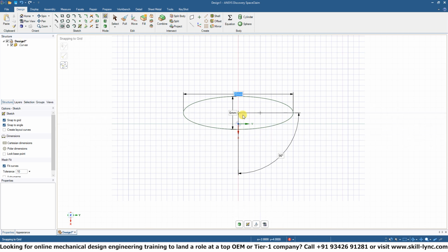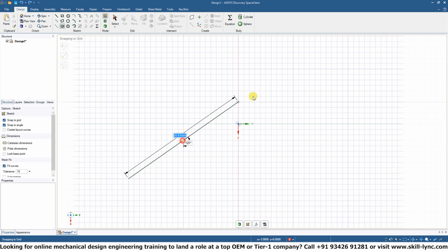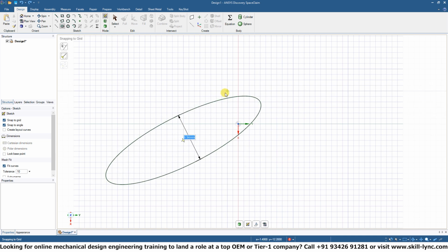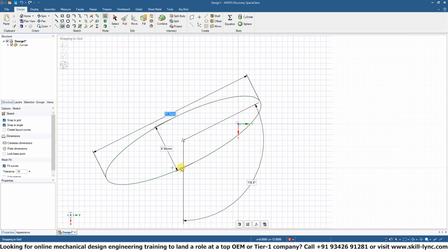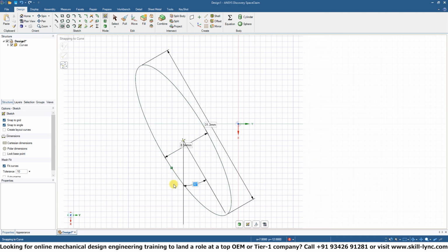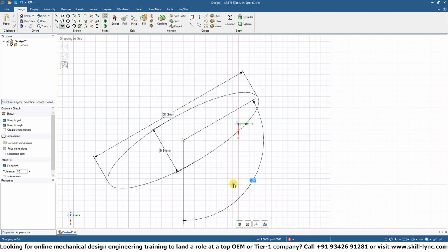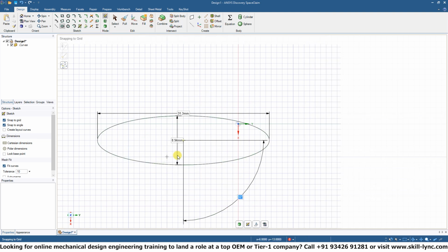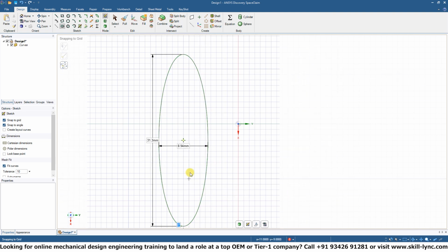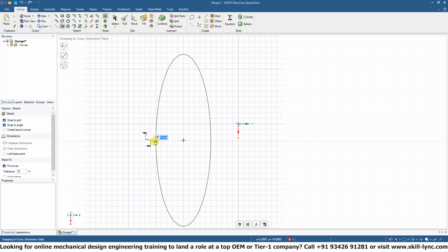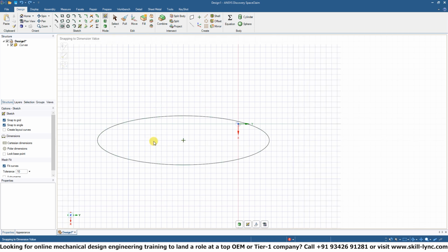That works. It gives you some angles over here because you can also do it diagonally if you wished. It gives you the center line of the ellipse, and the angular dimensions from the vertical. That's 30 degrees, it rotates it that way. Obviously more than 90 if I put 120, it rotates it that way. 90 is perpendicular to the vertical, 0 is along the vertical. You can edit the width and obviously the height of the ellipse as well.